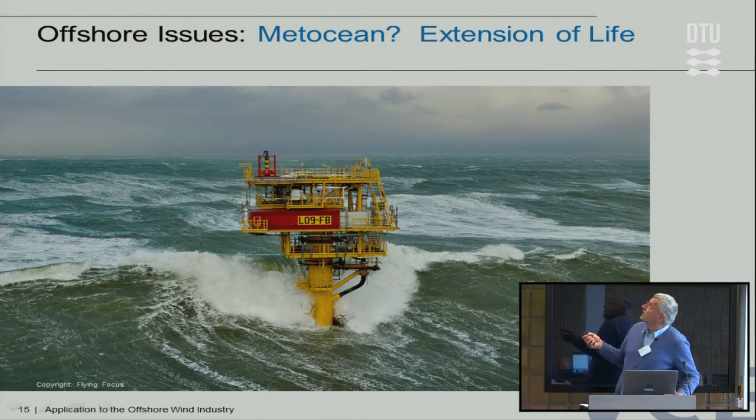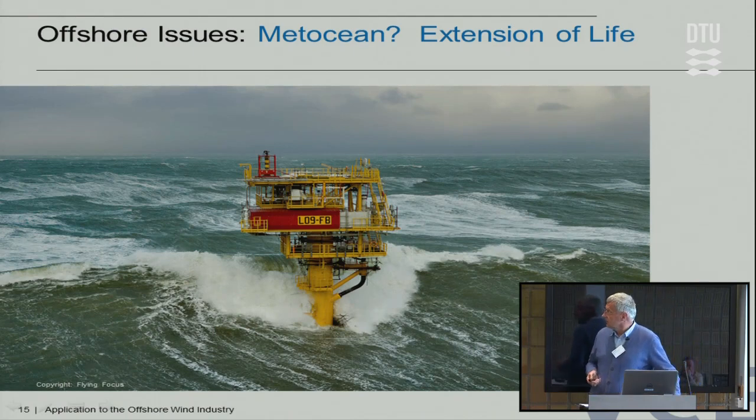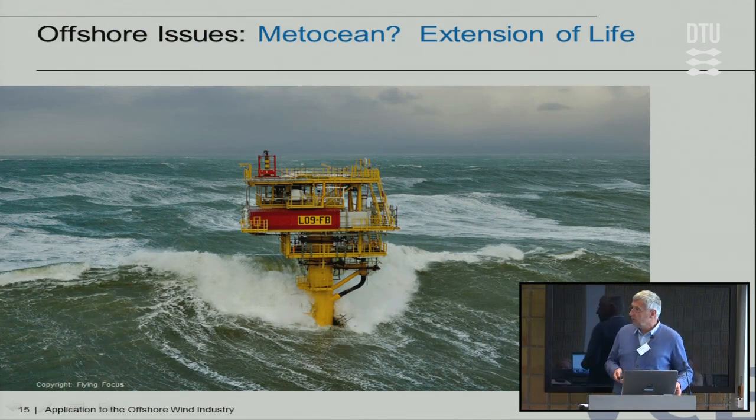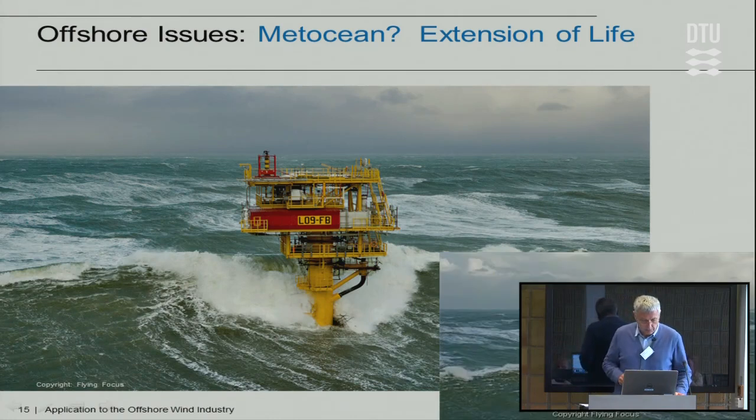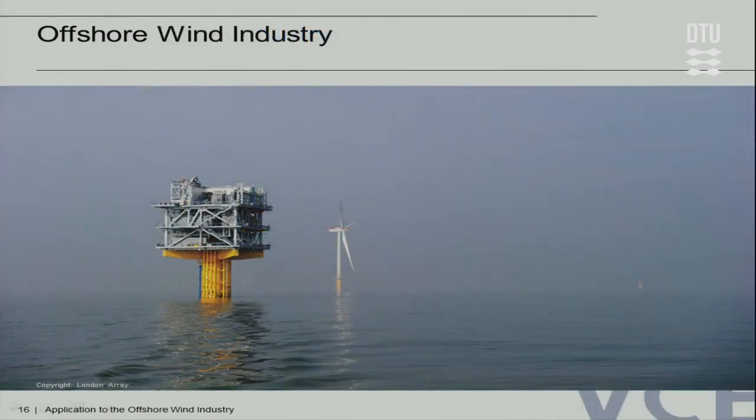Interesting is that this Met Ocean data, for example in the North Sea, has changed considerably. What you can see here is definitely not what this platform has been designed for. The wave height was 16 meters 10 years ago. It's now 25.5 meters. And the difference is what you see here in this picture. Of course, we sometimes have less strong situations like this one, but we have these two types.